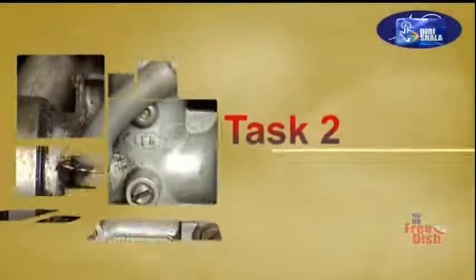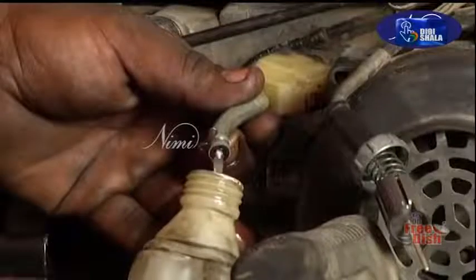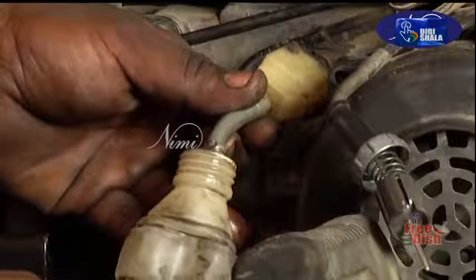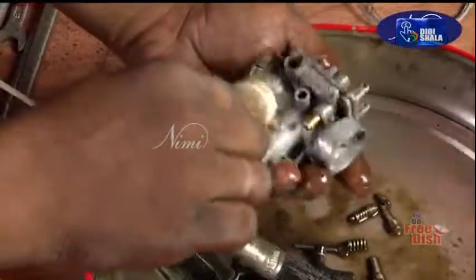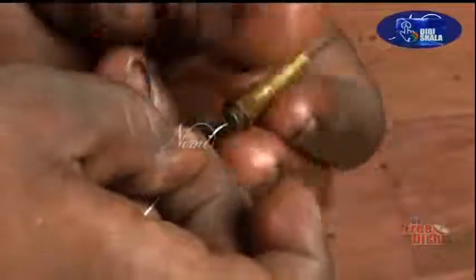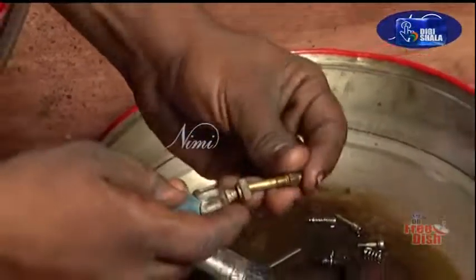Task 2. Clean the carburetor. Collect about 50 ml petrol from the tank by opening the fuel tap and clean all the components thoroughly. Kerosene may also be used. Check the main jet for any block, insert a small wire, clean the gap and blow compressed air to remove any dust.